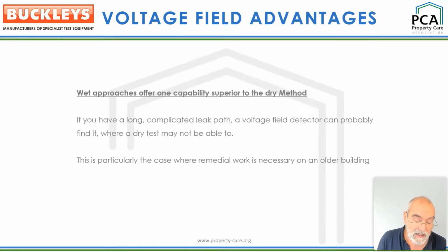The voltage field wet test approach is ideal for surfaces that are substantially level, smooth and do not have numerous grounded items within the area to be tested. It's also the preferred method to be used when it's raining. If there's one takeaway, the wet method is likely to give the quickest results in locating the sources of leaks in old buildings where established leak paths are known to exist.